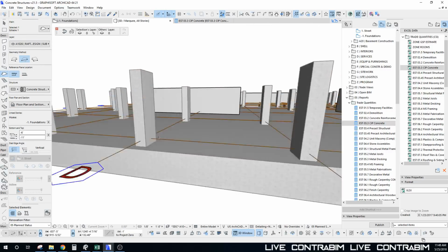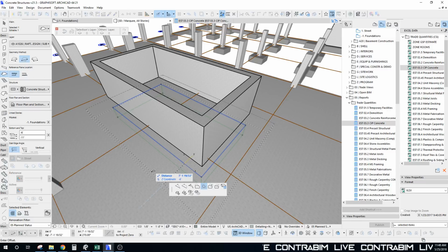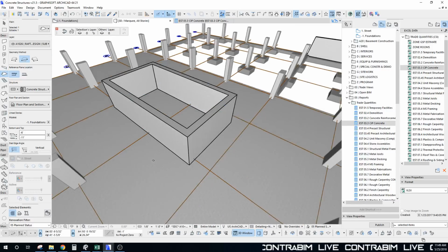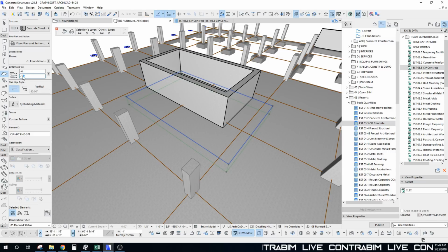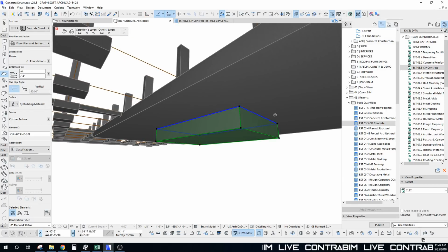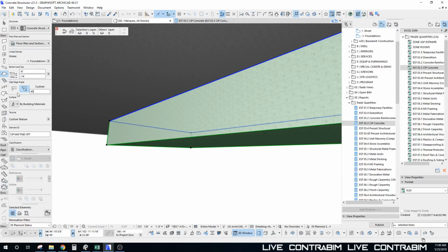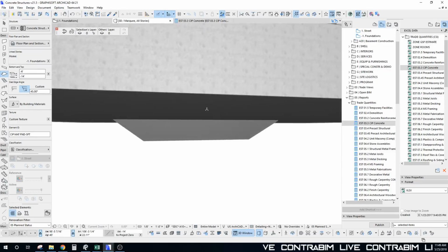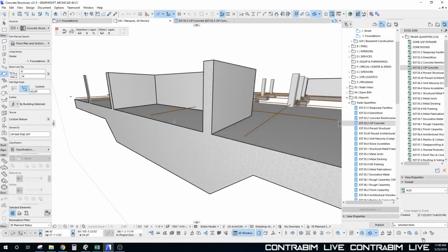And what we can do is simply offset this and get that to extend out a bit on each side. So what are you going to do, John? 8, 10 feet, 8 feet. And a little trick to get a nice slope on this: you're changing it to a much more thickened section, 14 feet below. But what you can actually do here is if you change the angle on this to 45, you can give yourself a nice little slope, which a lot of these deep sections below your foundation typically have.